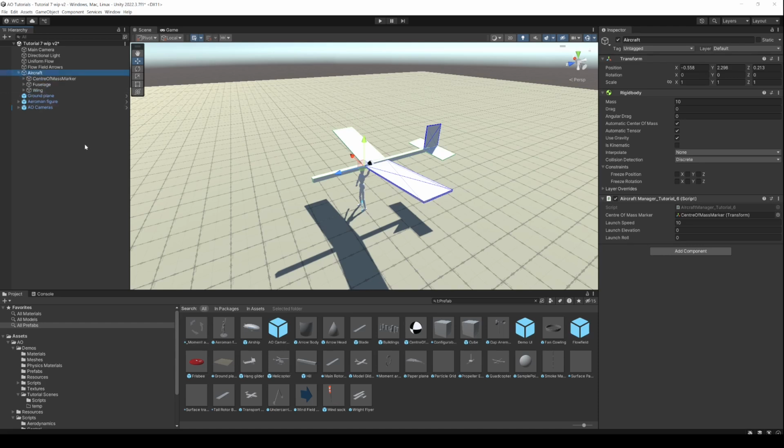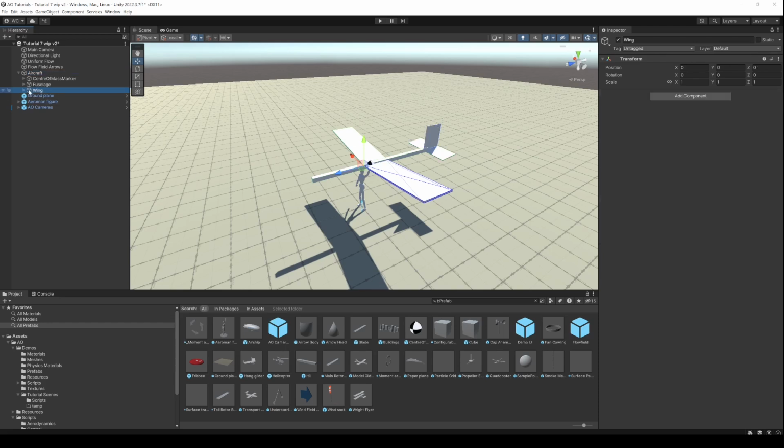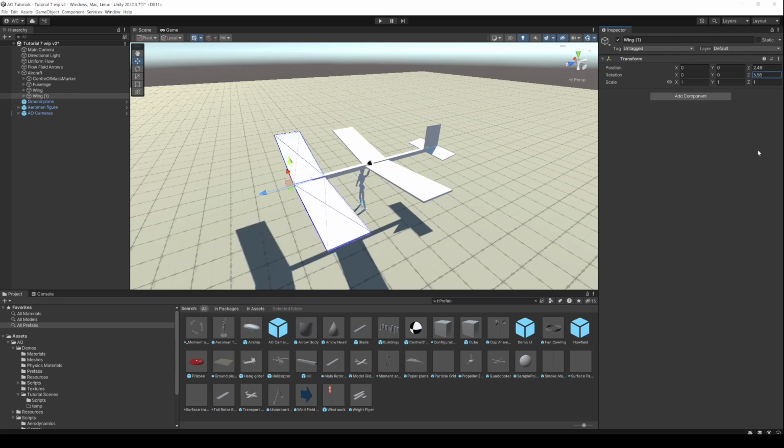Expand that out. And because we're smart and lazy, or maybe just lazy, we are going to create a propeller by reusing the wings. So what we can do is duplicate the wings and drag them forwards. This may look a bit crazy, but you soon get the idea. If we have them there, and if we can rotate them around the Z-axis and twist them a bit, we can make ourselves a propeller. And that saves us rebuilding a lot of the stuff we've already got on the wings.